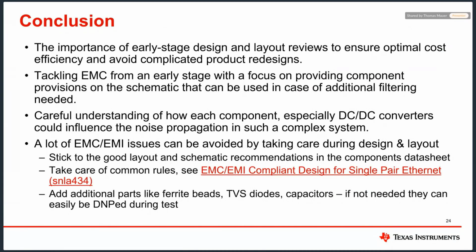So you're focusing on providing component provisions in the schematic so you can do additional filtering when needed. Also, it's important to understand how each component, especially the DC-DC converters, can influence the noise in a complex system. So a lot of these EMC and EMI issues can be avoided by taking care during the design and layout.